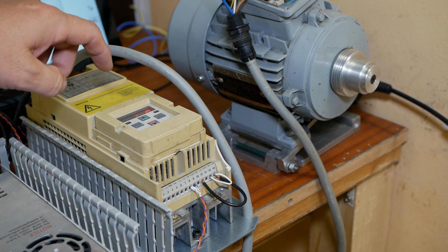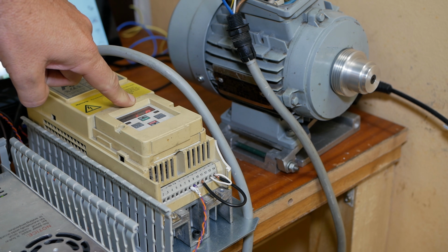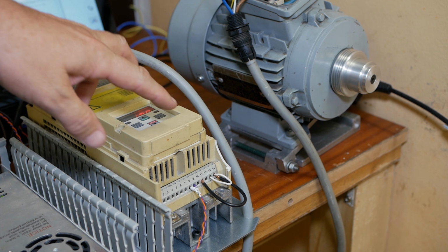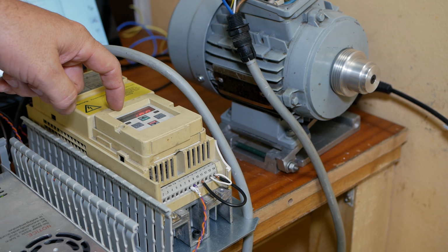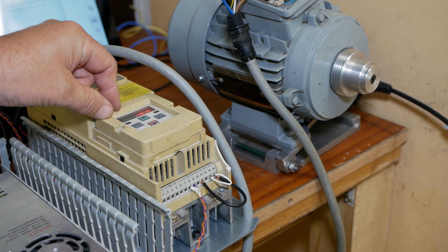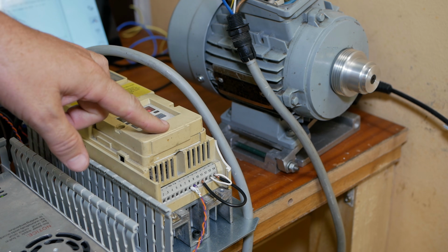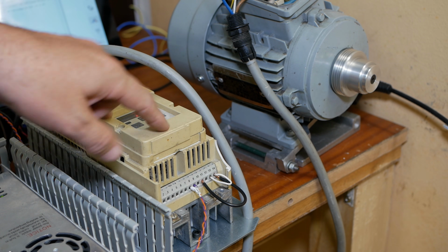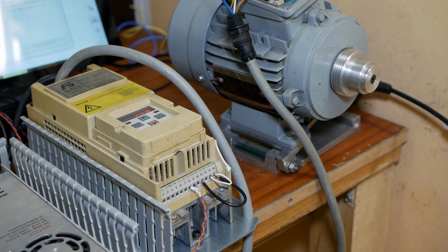Well, it looks like I've set up the VFD for full speed command equal to 100 Hertz, whereas of course line frequency here is only 50, so I need to adjust the scaling to make sure that this runs the motor at the correct speed. Although I might even leave it at that and just adjust everything else and accept possible high speeds. I guess we'll see once we've got it on the lathe. Based on that, maybe I would have been better off putting a smaller pulley on here, but it is following the speed command, so that's good.